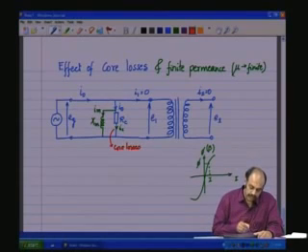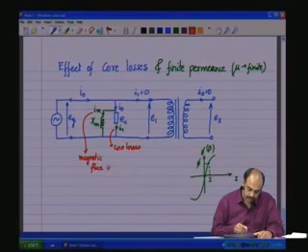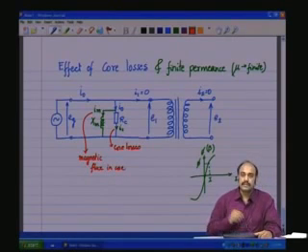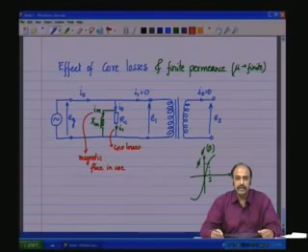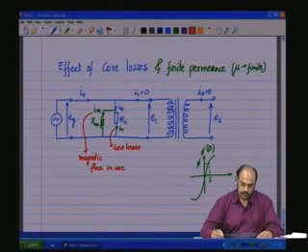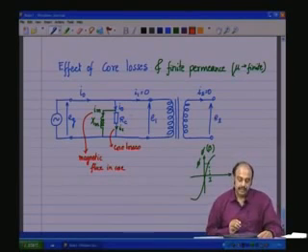IM is that component of I naught which produces the magnetic flux in the core, such that it can be linked to the secondary and have an induction on the secondary side. So these two non-idealities result in such an equivalent circuit.